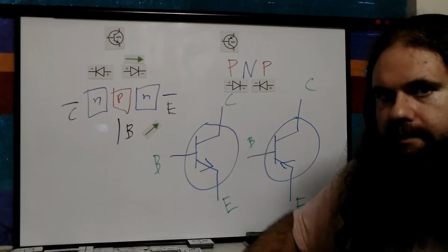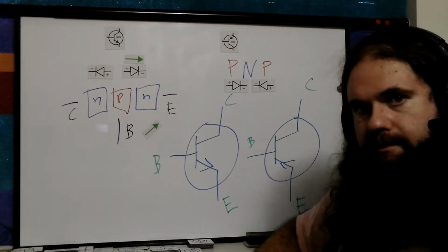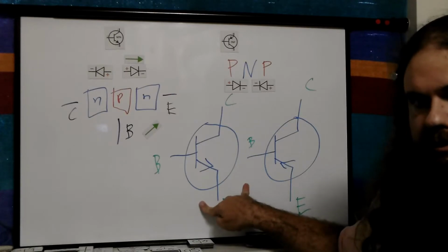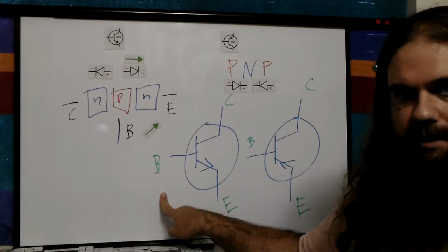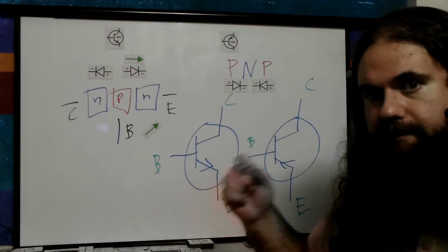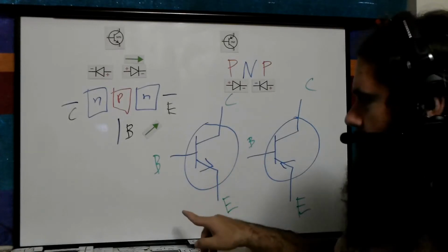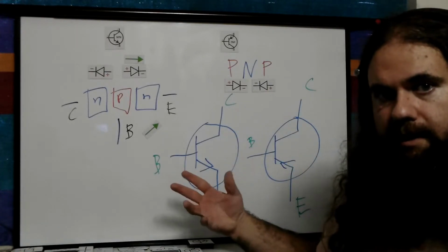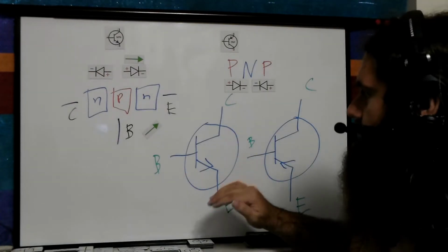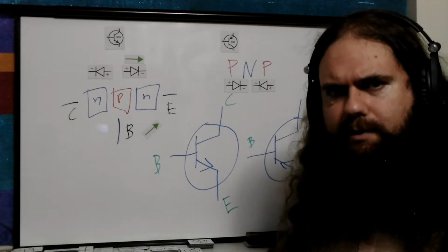Don't overcomplicate it. Just think of two junctions, think of three ways to turn them on and off, and there you go. And as a reminder, these are current controlled. Forward bias or not forward biasing, the voltage does not matter after that. You forward bias with 0.7, 0.3, whatever volts, according to whatever transistor you're using. If you forward bias, the junction is biased. If you don't, it's not. And after that, it's current. And MOSFETs, of course, don't work that way. But we'll worry about that later.